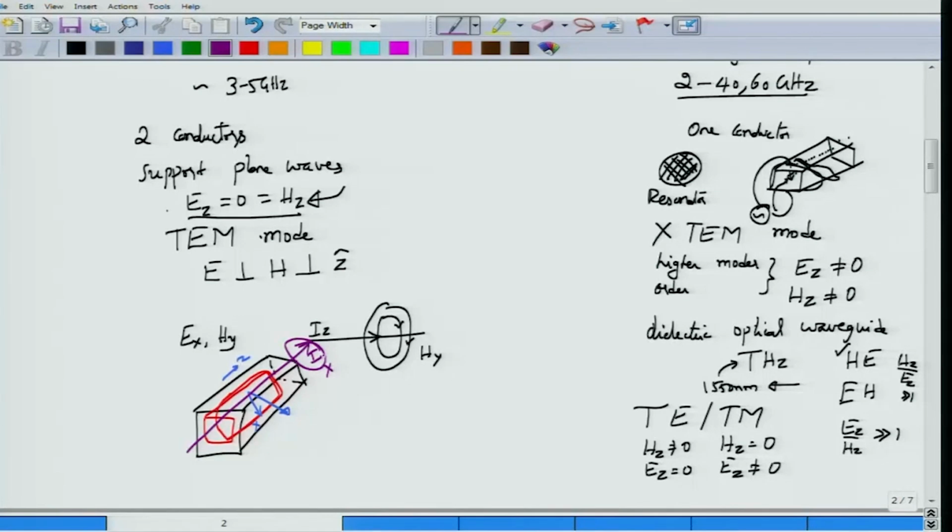Okay, if you don't have a conventional current, that is all right, you can still have the displacement current, so del E by del t, right. So you can have del Ez by del t, but unfortunately that is also not possible, because we have said that this is a plane wave structure, so Ez is actually equal to 0. So because there is no longitudinal current, you cannot have magnetic fields, and because of this reason you cannot have only Ex and Hy components which form the plane wave, or which actually form the transverse electromagnetic mode structure. Therefore, waveguides do not support a TEM mode. Okay.